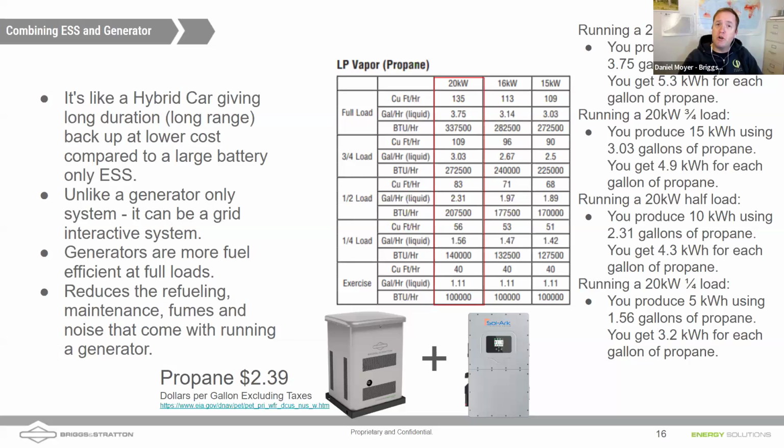But with DC solar, as has been explained, the solar can be either grid following or grid forming. When it's running off of batteries, the solar is grid forming, which can then adjust the frequency of the sine wave to curtail AC coupled charging. But when we start up a generator, it's a grid following inverter. So that removes our ability to adjust the sine wave to curtail. I think we're going to show that.